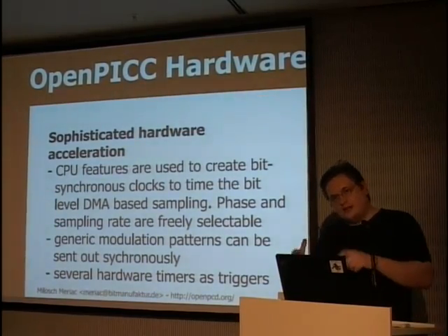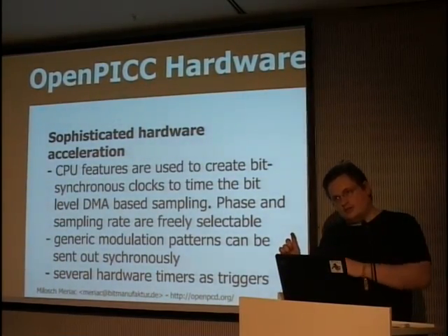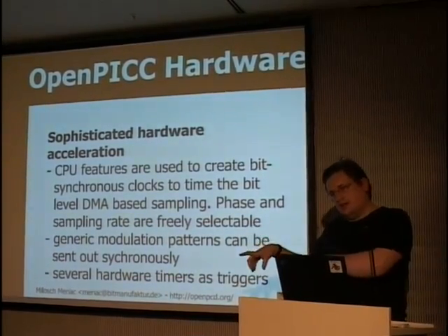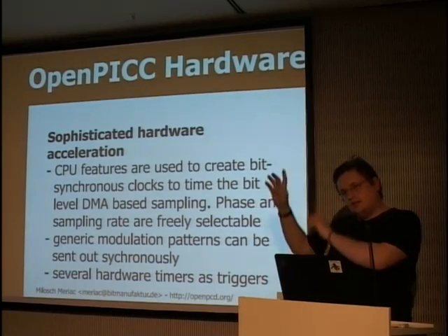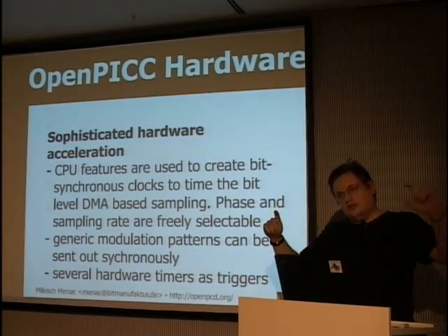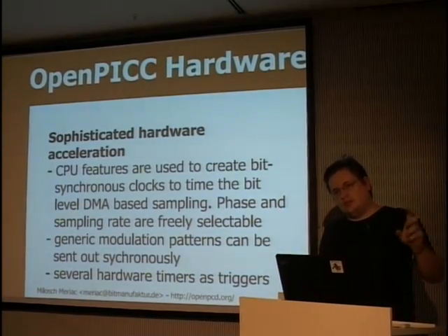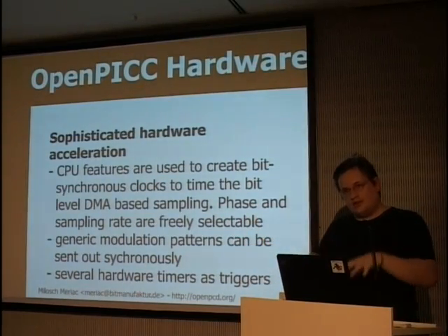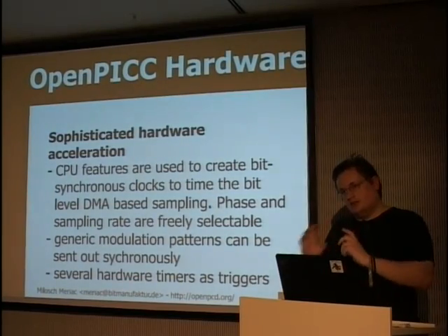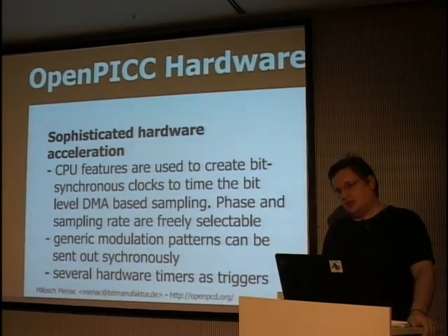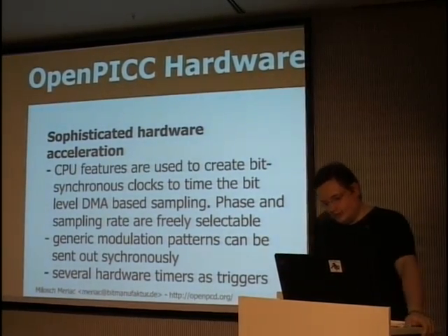And now you also understand why you have all these debug output features on the OpenPCD device, these U.FL outputs, because you have these U.FL outputs on the OpenPICC. You can create your modulation patterns, see them on one channel on the oscilloscope, and you can see how they result in demodulated patterns on the OpenPCD. So you have the whole chain, and you have full control of every aspect of the protocol, of the analog part, of the digital part, and you can quickly resolve problems. And it proved to be very, very helpful already.